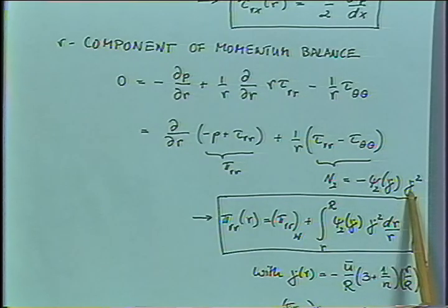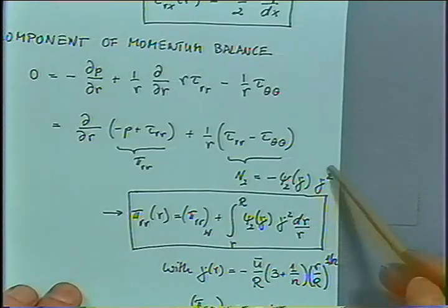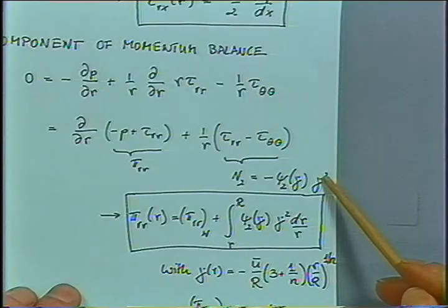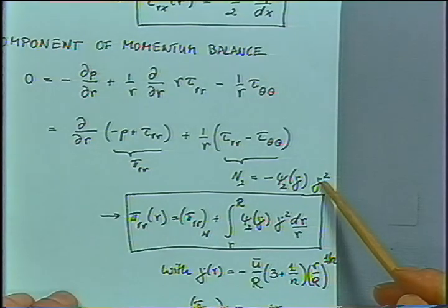Note that this shear rate square comes from our solution from the power law model. So to calculate the stress components here, we need the kinematics, which we calculated earlier. It doesn't come out a priori from an experiment. We have to derive that. And if there's a mistake in that shear rate, because our power law model has some limitations, then we carry this mistake into our analysis.